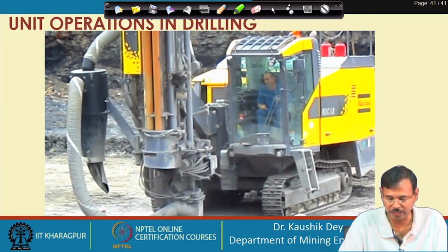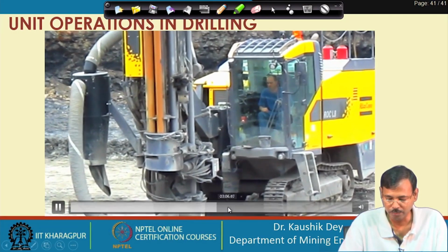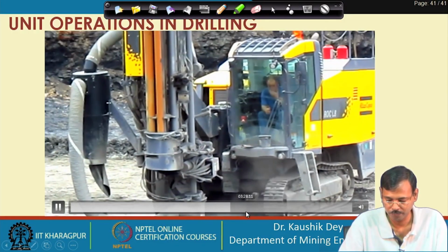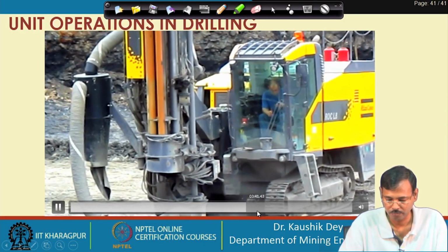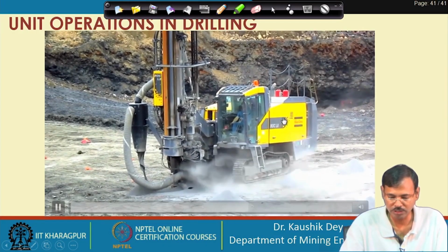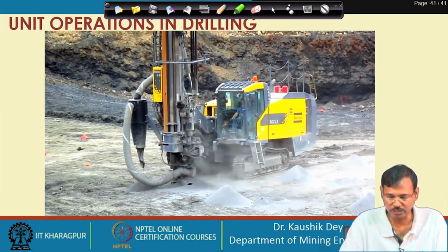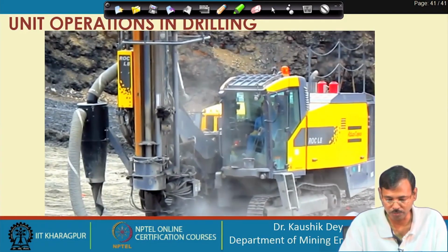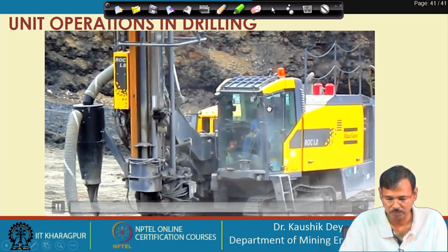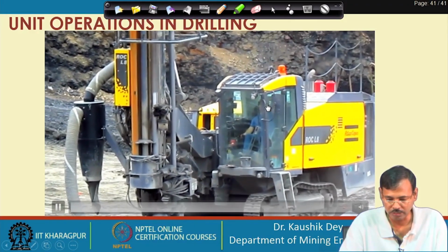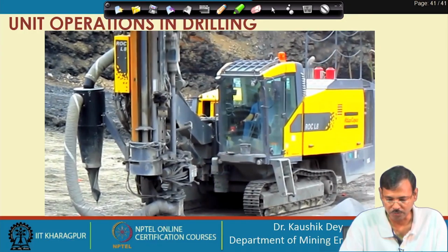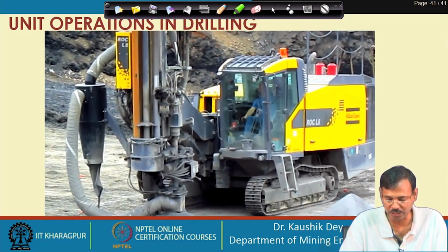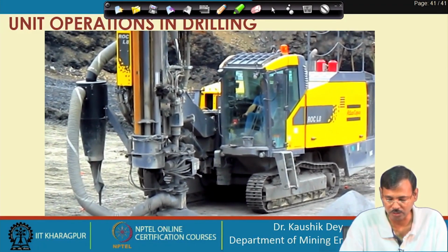So, now the penetration, as per the penetration rate, the drill bit is penetrating the rock and going inside the hole. So, now you can see the first rod is almost in completion stage. So, the first drill rod is now complete. And this is basically the first drill rod drilling is complete, the hole is now clear, trying to be flushed out if anything is there or not.